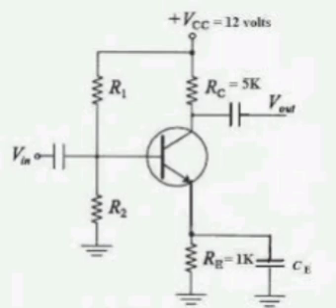The answer: 10 kVA, 2500/250 volts, single phase transformer, HV R1 equal to 2.4 ohms, X1 equal to 6 ohms, whereas on the LV side R2 equal to 0.03 ohms, X2 equal to 0.07 ohms. Primary supply voltage equal to 2500 volts, load equal to 5 plus j3.5 ohms at 0.8 power factor lagging. Secondary terminal voltage is equal to how much? Circuit referred to secondary: a equal to 2500 by 250, that equals 10.